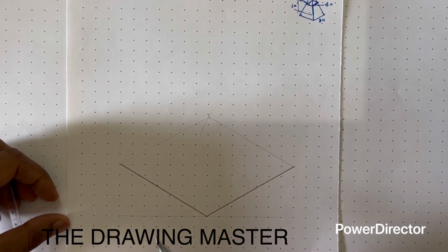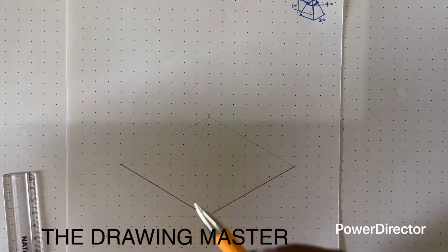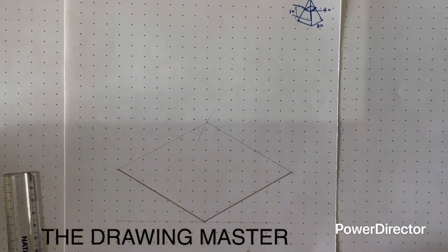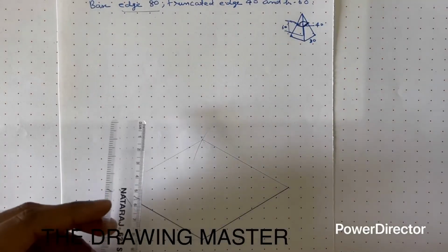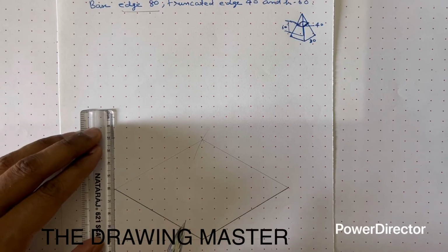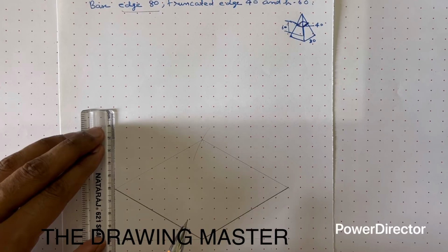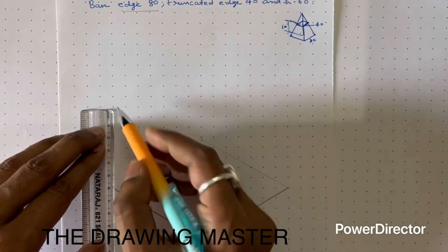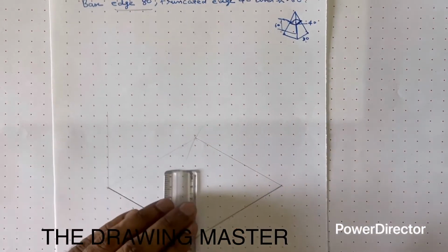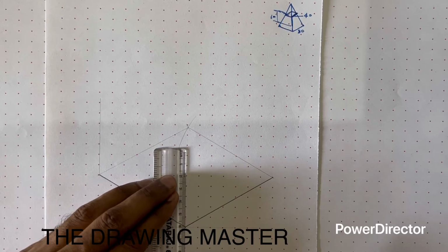After the construction of the base, the next step is to draw the height of the object. Now we'll create the height, as the height is given as 60. So let's take the height of 60 mm from all the four vertices. We'll start from here. Now from here also we have to take 60.